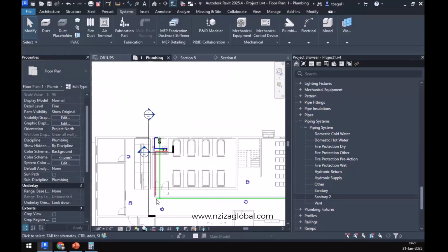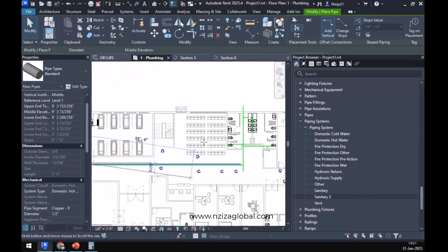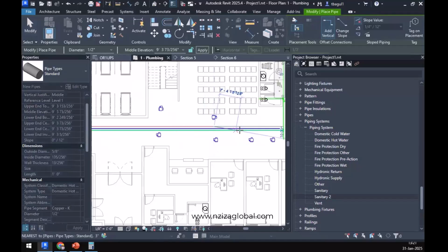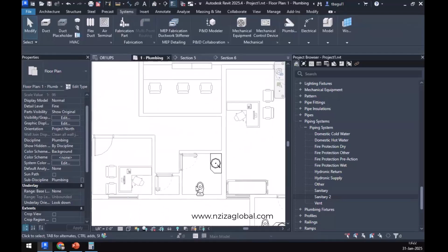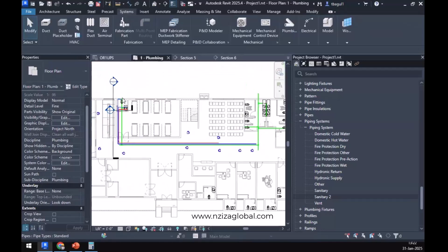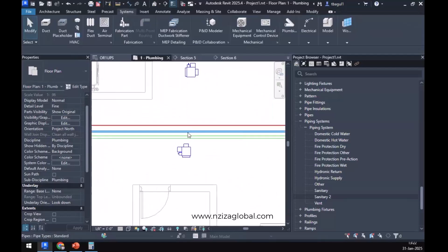And then we have this particular pipe as well that will bring till here, right? So now over here, we have this particular lavatory and this particular water closet, right? So now water closet WSFU 5, this one 1.5, right? 5 plus 1.5 plus 5 over here plus 1.5. So 6.5 plus 6.5, 13, right? So at this point, what the cold water line needs to be sized for is 13 WSFUs.